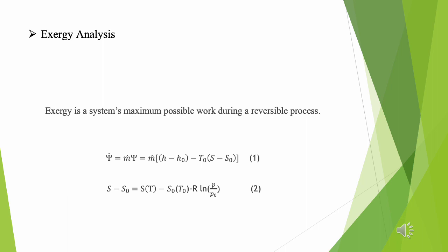As we mentioned in the previous slide, and according to experimental data, the best result will be obtained at a pressure ratio of 0.099. That is a ratio of extract pressure to input pressure. So in this case, we have maximum ratio of output pressure to input pressure in all cases. So according to equation 2, we have the minimum amount of delta S, and also we have maximum amount of exergy in all cases, which is our final goal.